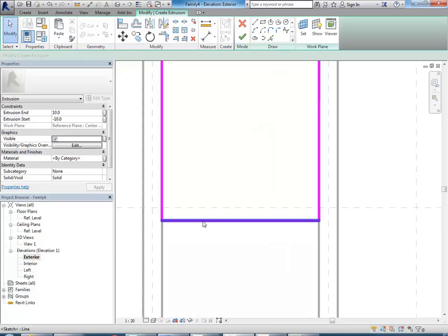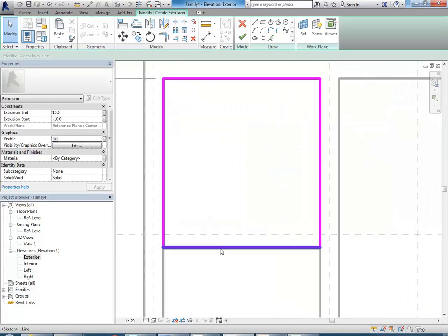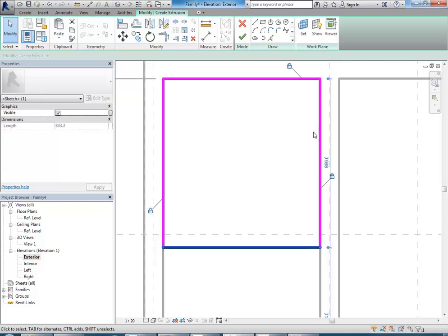Okay, so do you want to be brave and guess, if this is the top sash, and I've got a 40 mil frame or sash thickness, how far below that centre line would this line be if this is the outside of my sash? Does someone say 20? Yes, spot on. Yeah, that's right. So 20 mil below. That's right. Half your thickness.